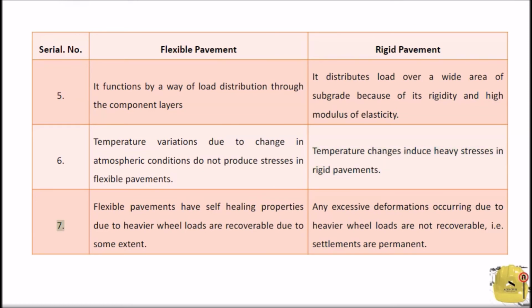7. Flexible pavements have self-healing properties; excessive deformations due to heavier wheel loads are recoverable to some extent. Rigid pavement: any excessive deformations occurring due to heavier wheel loads are not recoverable, i.e., settlements are permanent.